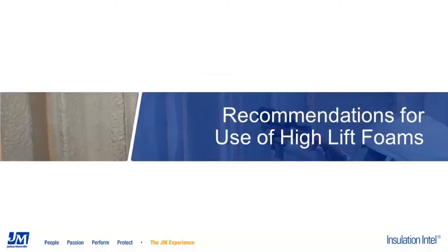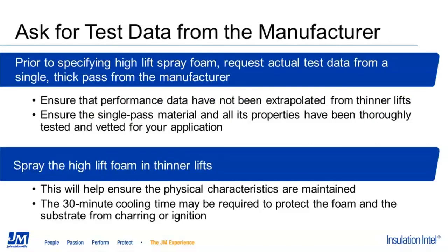Thank you, Chanel. So Johns Manville has 3 separate recommendations for the use of high-lift foams. The first solution we have is to request actual test data from your spray foam manufacturer prior to specifying or installing a high-lift foam. Ask for data that was generated on samples that mimic the conditions you are specifying or installing to. Ensure that the data listed on the datasheet or other documents has not been extrapolated from thinner passes. Also, ensure that the material and all physical properties have been thoroughly tested and vetted for your specific application.